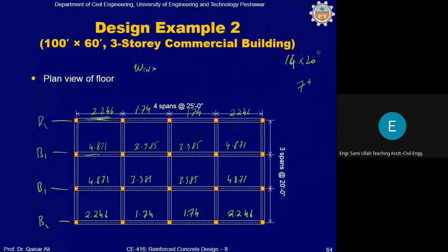So the cross-sectional area of the web gives the self weight of the web. It is equal to the cross-sectional area, 14 by 13 divided by 144, multiplied by 0.15 and multiplied by 1.2. This is the self weight of the web. You have to add this value to all these values. Calculate.